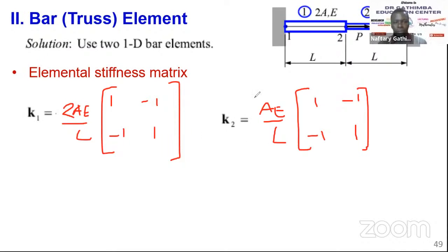So that's the elemental stiffness matrix. Step number 2, we need to get the combined stiffness matrix, or the global stiffness matrix, for the overall structure. Remember the superposition principle? I was encouraging you to really practice on that, so that you do not use the force-displacement, the force equilibrium equation method, that is going all the way back from the basics.